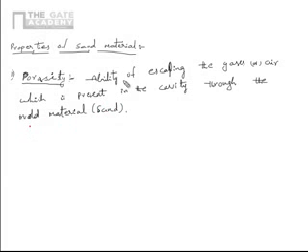So how to determine the porosity? Porosity increases with decrease in clay. As we have discussed, clay acts as a bonding agent between each sand particle, and this clay goes and occupies the minute space between each sand particle.